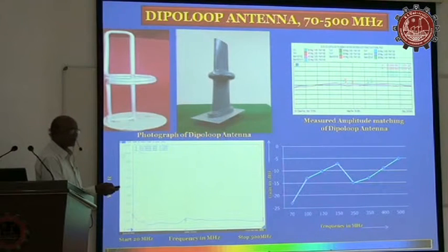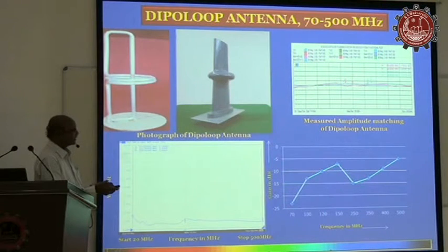When radars operate at 70 MHz, most radars use vertical polarization, but these low frequency radars use horizontal polarization. A 70 MHz horizontally polarized antenna you can make, but it has to respond for both vertical and horizontal. Such an antenna does not exist as of today.